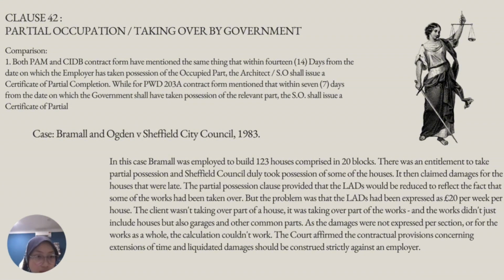Next, clause 42, partial occupation taking over by government. For comparison, both PAM and CIDB contract forms have mentioned the same thing, that within 14 days from the date on which the employer has taken possession of the occupied part, the architect or SO shall issue a certificate of partial completion. While for the PWD 203A contract form, it mentioned that within 7 days from the date on which the government shall have taken possession of the relevant part, the SO shall issue a certificate of partial completion.